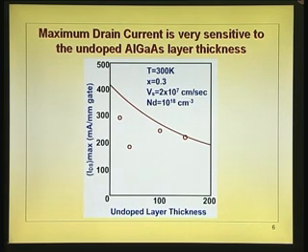Now, about the spacer layer, undoped layer thickness. These are some of the experimental points people have made. I think the Illinois University or so, they have made some of these measurements. So, this is the maximum current that you can get as the spacer layer thickness is varied. That is understandable, ID is proportional to Cs. Spacer layer is thicker, Cs falls, ID falls. ID is the maximum current, means actually when the band bending is maximum.